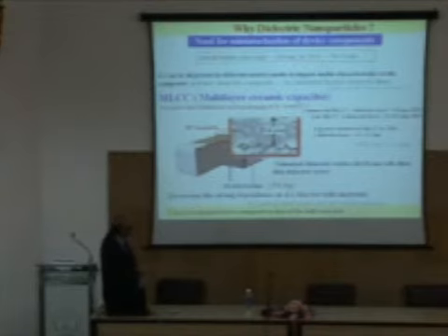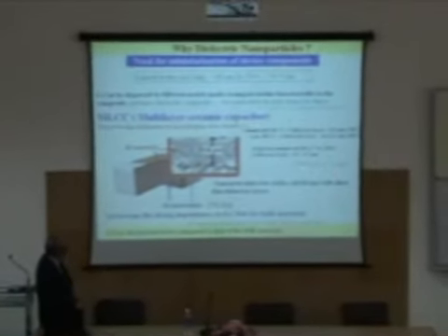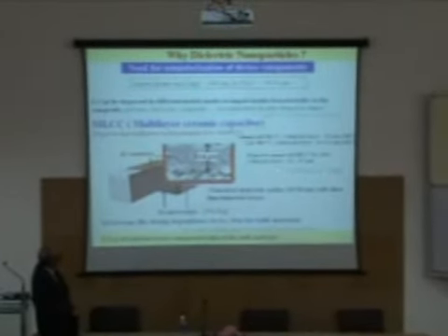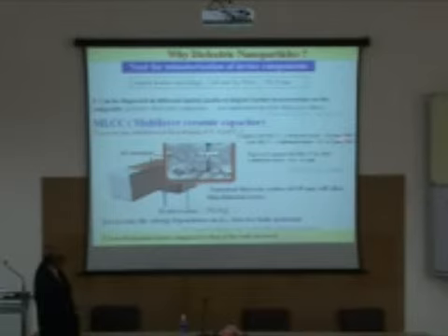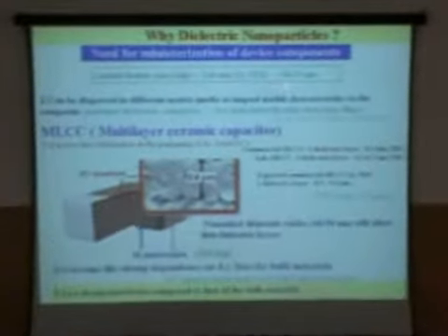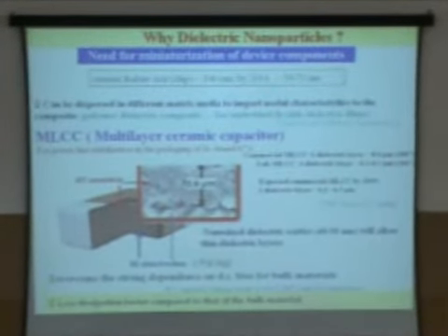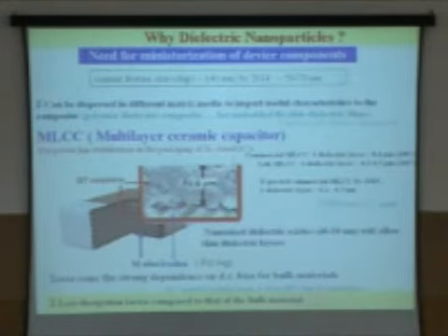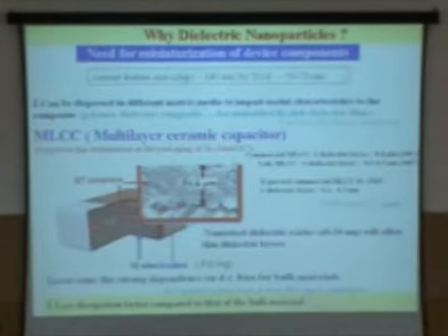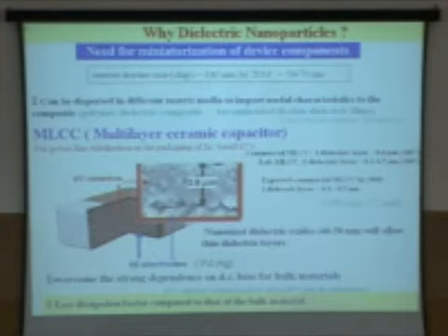As you see, the 1990 limit was 12 micron, we had already achieved 0.8 micron in 2007, and what is predicted for 2014 is 50 to 70 nanometers. The problem is you have to control not only the barium titanate, which is the basic material, you also have to control the nickel or palladium or silver electrodes within the multilayer capacitor.